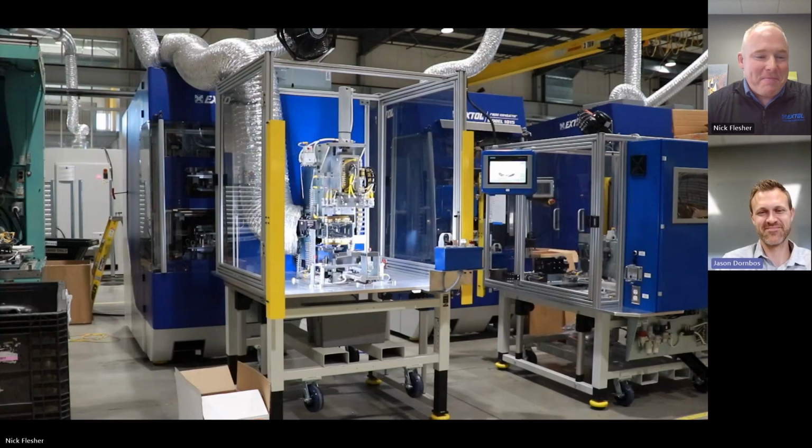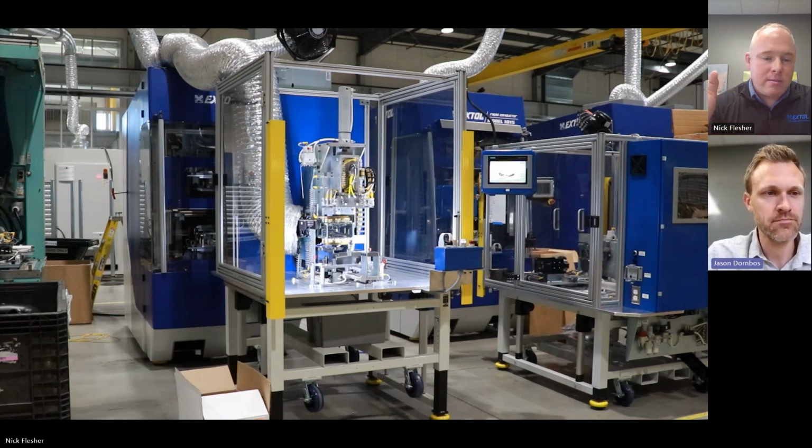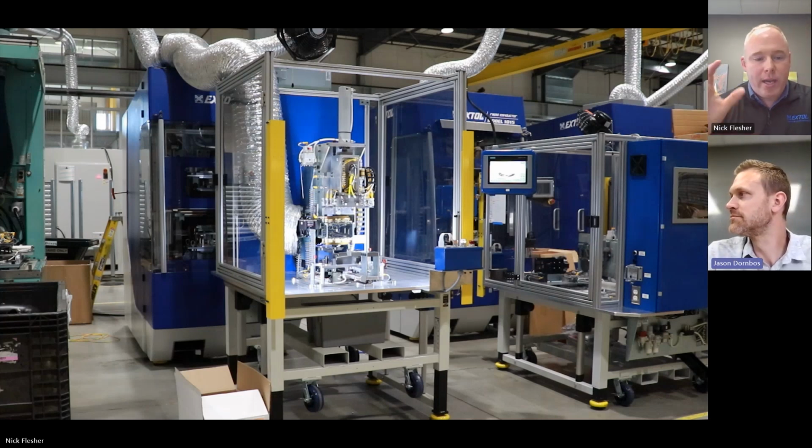What happened in that process there was, I'm going to play it again here in just a moment. You've got two parts, one in an upper press, one in a lower press. The emitters come forward. There's a melt time, as Jason described during InfraStake, where you can actually see the infrared energy on. And those emitters get out of the way, parts come together, and there's like, I think, a 7-second seal time in this. So that's the process in a nutshell. We're going to talk about how that breaks out to integration here in just a moment.